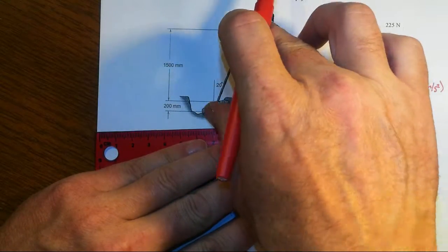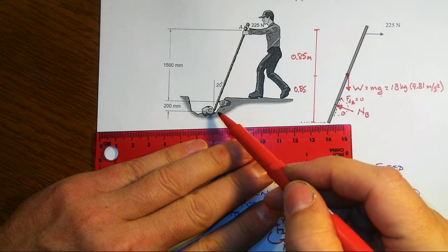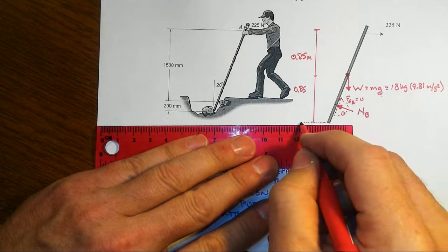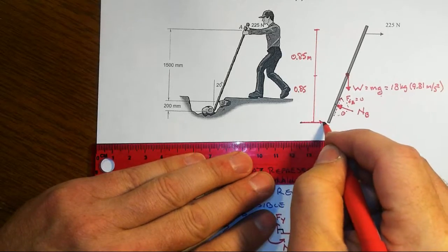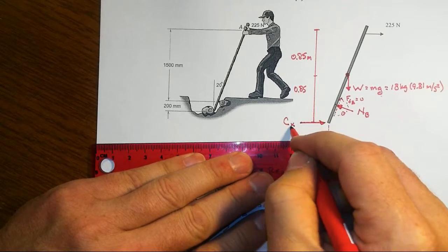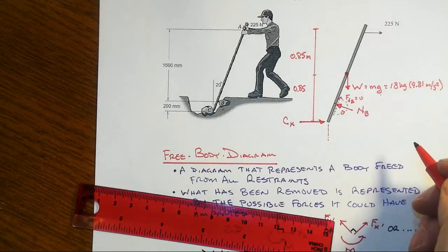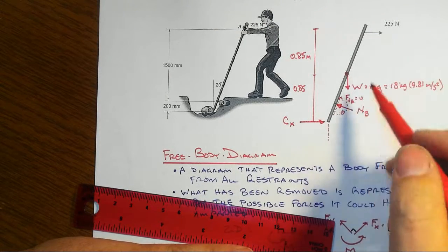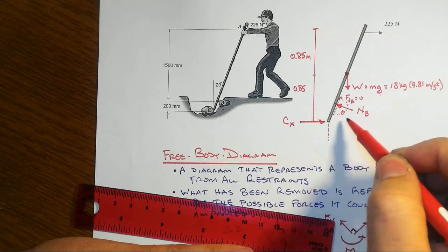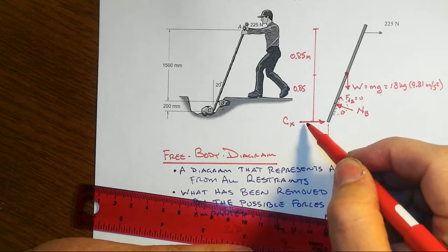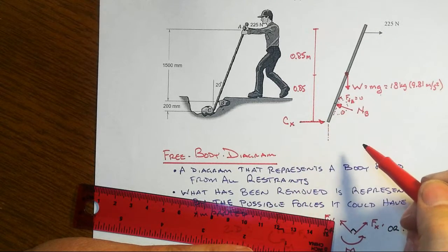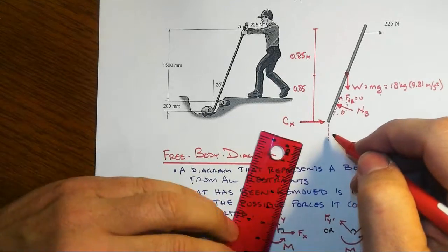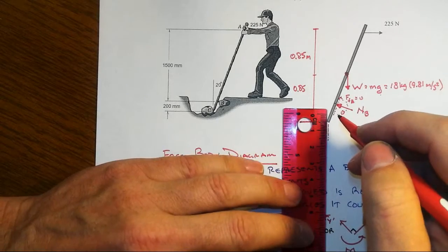Hey, this thing wants to rotate about point B. It's trying to shove the rock to the left, that means the rock is probably pushing back on the prybar. It's hard to believe that it would be anything but that. And that means that the x component of NB, when we do equilibrium sum of forces in x, is going to be the sum of Cx and 225. It's going to balance out that way, right?